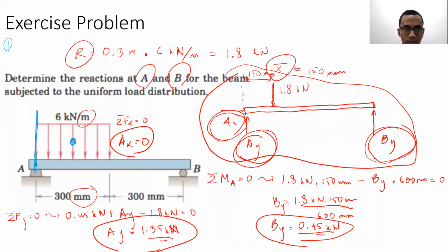Okay, if you are asked to find out the external forces due to a distributed force like this, then you can represent the distributed force as a concentrated force at a certain location. But later, there is a limitation on that. Sometimes you cannot do this. You can only do this to find out the external forces.